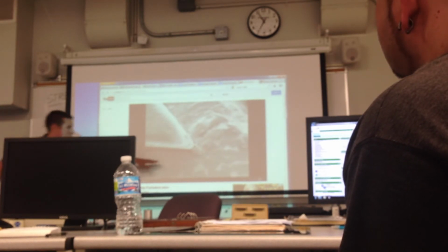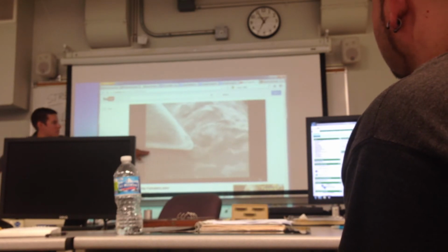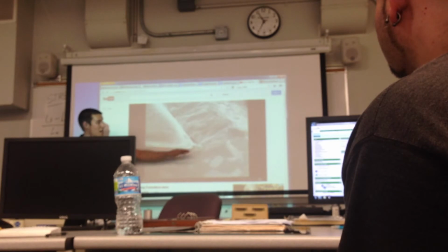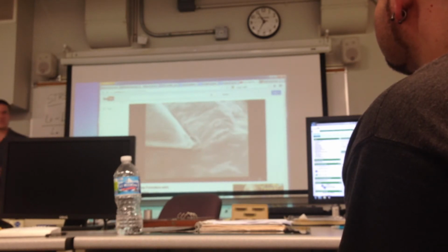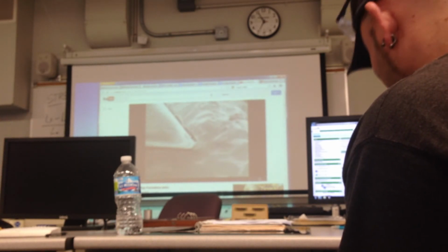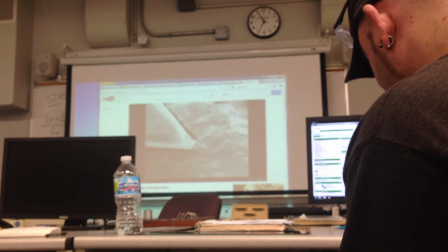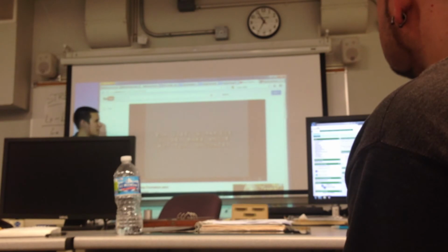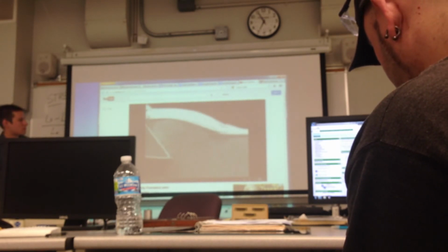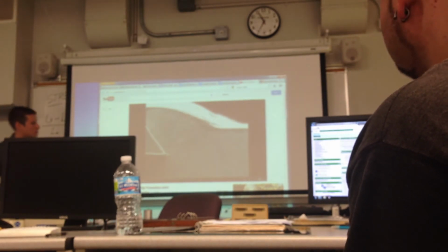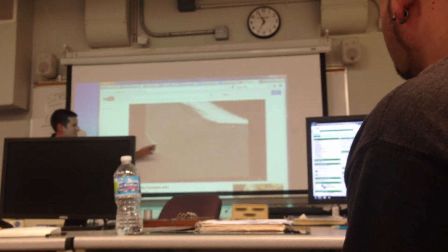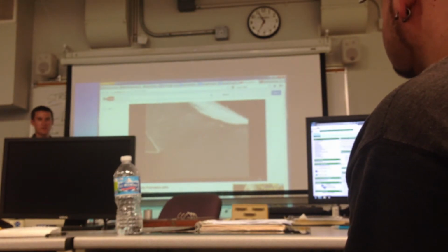Well, these things are breaking off of the burrs, right? That's a chip right there. But what you actually have right here is a built-up edge. So the tool is actually not doing the cutting. You're just shoving material into there, so it's making the tool a lot harder to work. That looks like butter or something. But still, you can see that the plane of shear is right there, almost at a 90-degree angle to that rake.